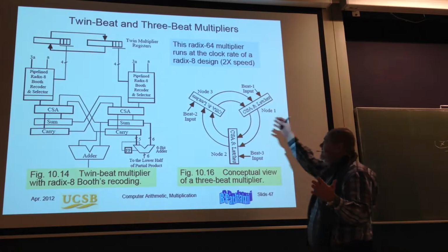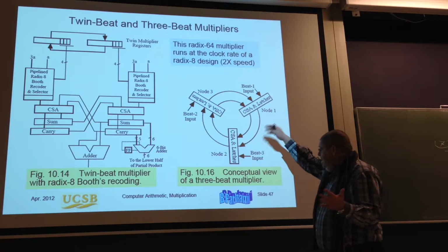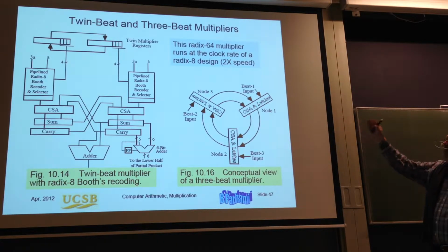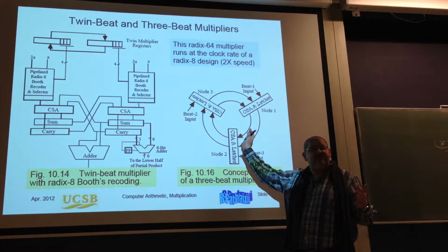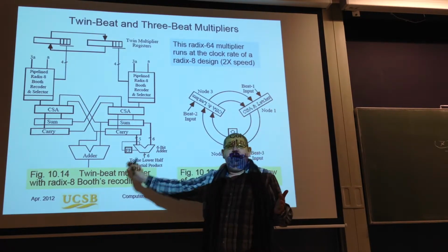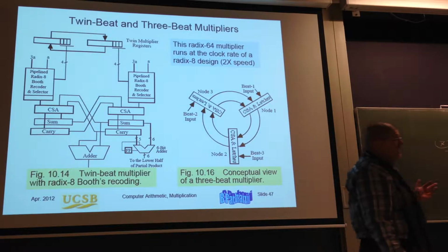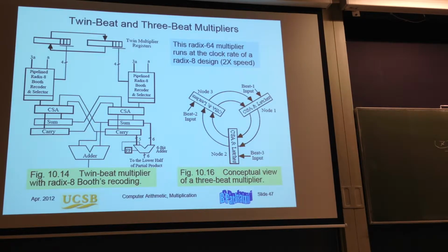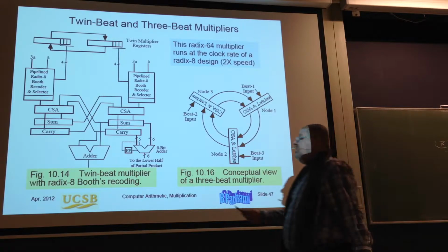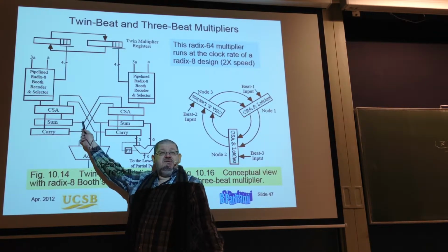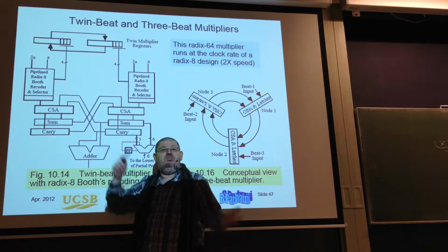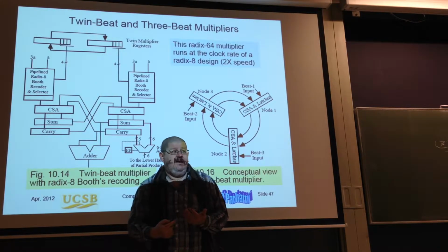Okay, and you can even push this to what is called the multiple bit multiplier, but this is more theoretical stuff. This you can do in practice. There are things, however, which you have to be careful about. You may have races, you may have glitches, because when you start the calculation in this one, you have to be sure that this one is available. If this one is coming a bit later, then you may produce wrong results.